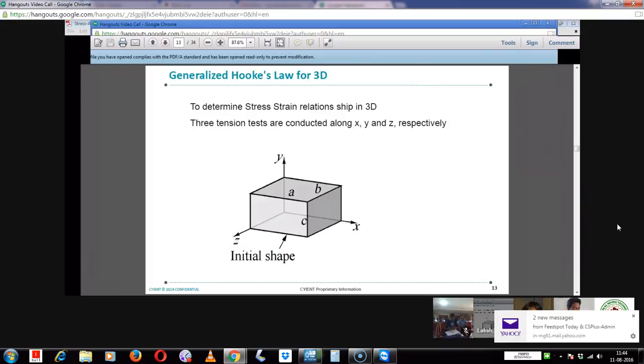So all loadings are applied uniformly throughout the 360 degrees. So no need to consider the complete 360 degrees. If you want to solve a 360 degree model, it is only for one case, that is, when the blade is released. Due to some assembly issues or failure issues, when the blade is released from the assembly, at that time you need to consider the complete 360 degree model.